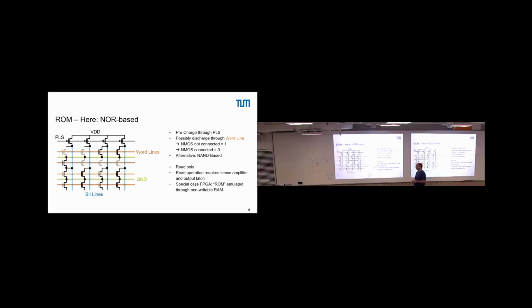There are some forms of ROM, such as electronically programmable ROM, EEPROM, or light programmable ROM, where you can reprogram a limited number of times. There are also one-time programmable ROMs where you implement this connection with fuses. If you want to program a specific word into it, you blow a fuse.